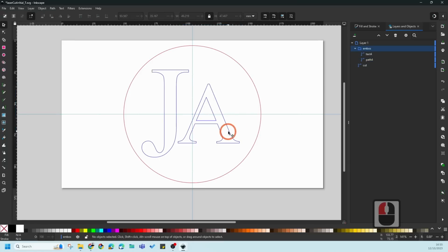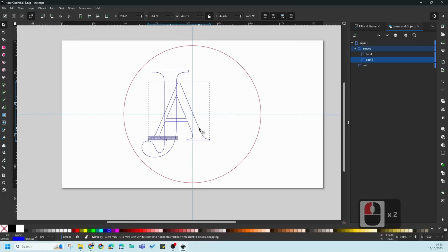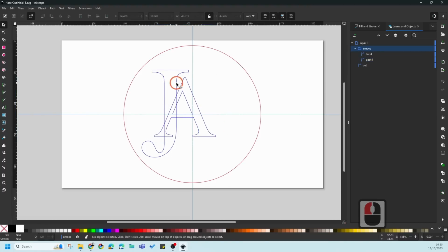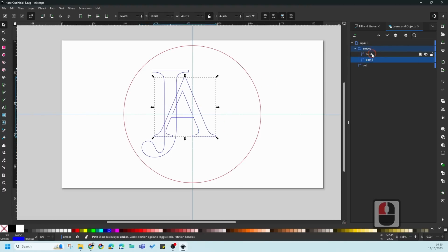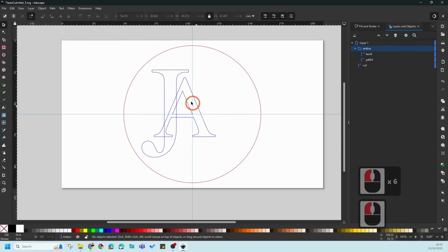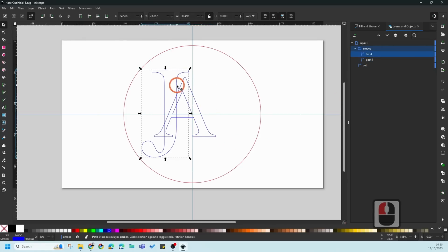cut. So you can actually put text over something else like this, for example, or below. So you've got these options, and just remember, while you're selecting objects, you can see what's up and below. You can also do a neat trick where you can minus one object from another, for example. So the J, for example, I want to use it to subtract from the A below.